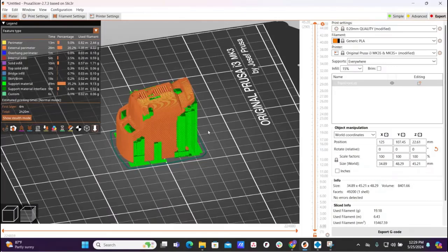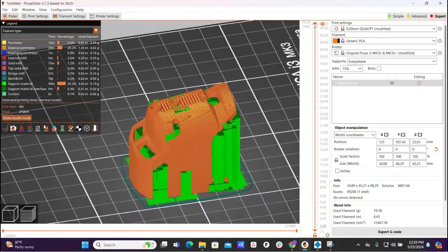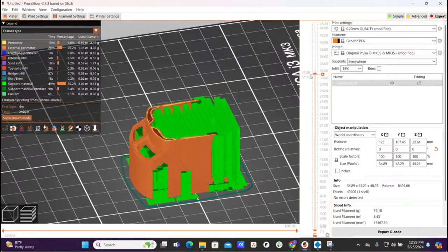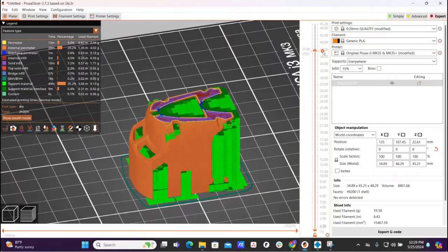One other thing I wanted to point out is when you're slicing, this slider is going to be your best friend. When I'm coming down here, you can see all the individual slices and cross sections of what the printer's doing, right? So if I look in here, right at the nose, this is where that 0.2 I mentioned matters. You see how there's all these little steps that are coming up here? That's kind of unavoidable right now in 3D printing. Since we're doing 2D layers stacked on top of each other, round surfaces at the top can end up with this little stair stepping thing.